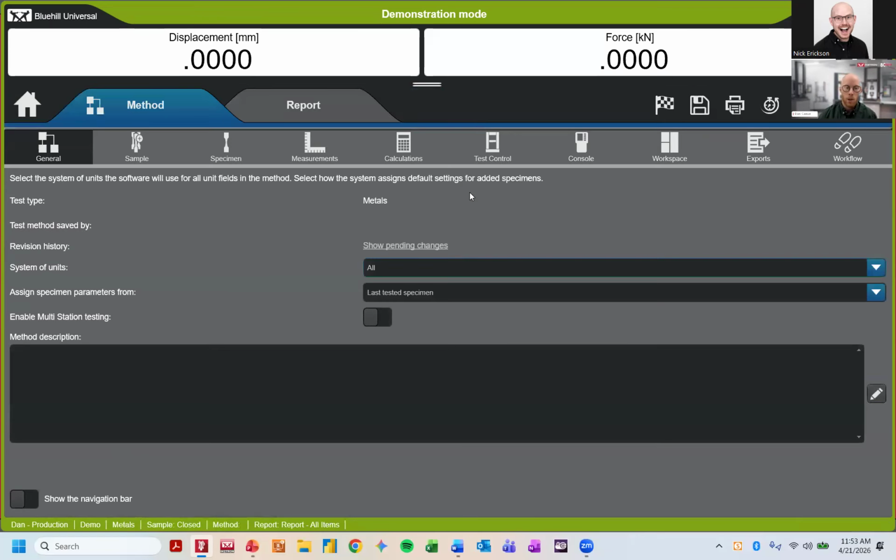Typically when you are measuring modulus, I guess it depends on exactly what standard you're referring to. But most modulus measurements do require a very accurate strain measurement that is only met by extensometry. But maybe you're referring to some sort of elastomer or some elastomeric standard or something.